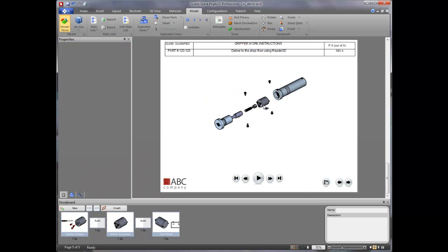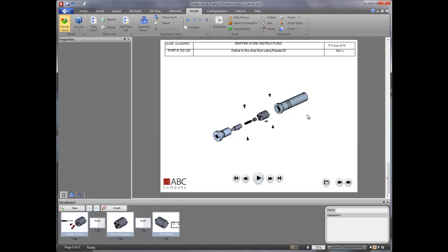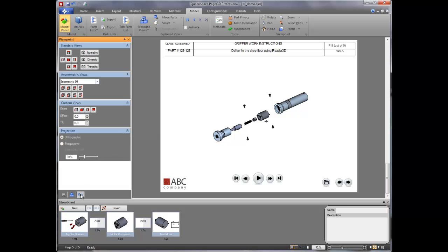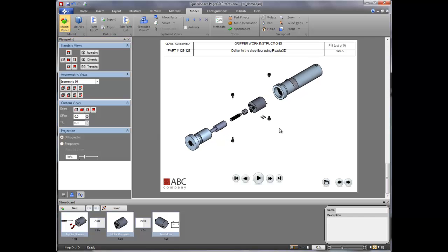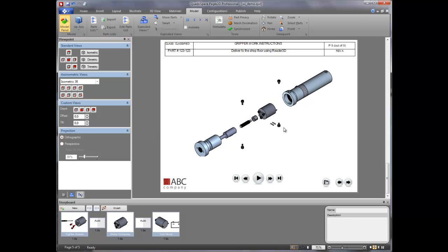So we now have this exploded view, and we're ready to create a new storyboard of that assembly process. The first thing you want to do before we go into using Smart Template technology, or our storyboard wizard, is set up exactly how the view looks. I like this. It's nice, crisp white with lined solids. And the viewpoint is going to be kind of like the template that the automation tools are going to use. So let's just take a good axonometric view, this isometric view here.